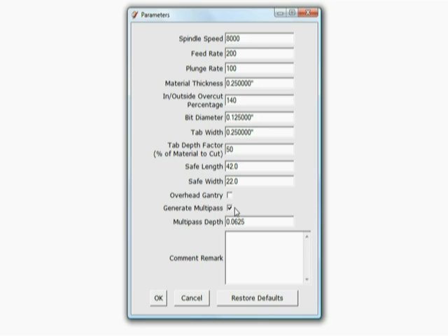And in actuality, you could probably plunge the bit fully into the substrate, MDF, depending on what bit you're using. Well, you would have to go so slow of a feed rate so that you don't burn the bit up or friction fire the wood. Then it would take you hours to cut out your parts. Whereas if you keep your machine speed up, in this case, if it were MDF, I would do 40 inches per minute and take maybe 1/16 inch passes. Well, I could finish this whole file in 20 or 30 minutes. So that's just a little bit about multi-pass.